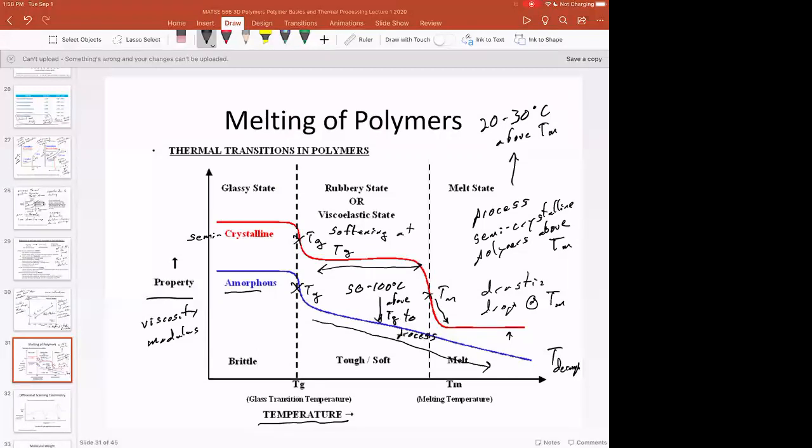So this depends on the polymer. And so you really need to think about what is the polymer, what's known about its viscosity as a function of temperature. You really need this type of rheology plot or modulus versus temperature in order to design a processing scheme. But this gives you some ideas of what you look for when your boss comes up to you and says, I want to thermally process this polymer in material extrusion AM. Can you figure it out for me?